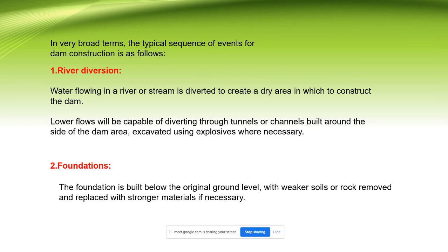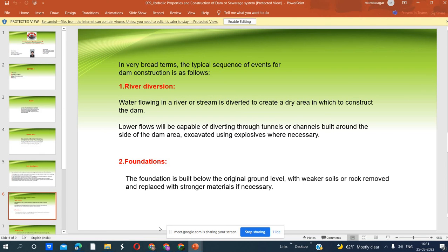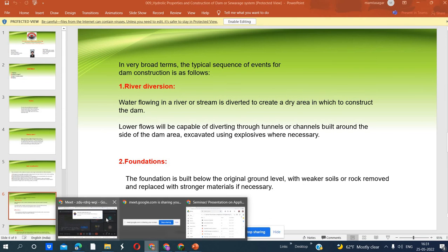Now finally we are talking about the safety of the dam. The Reservoirs Act 1975 is the updated version of the Reservoirs Act, which institutes safety law for UK reservoirs holding over 25,000 cubic meters of water. The dam can also be inspected for signs of water leakage under the earth, which can gradually create an unstable cavity. Thank you, ma'am.